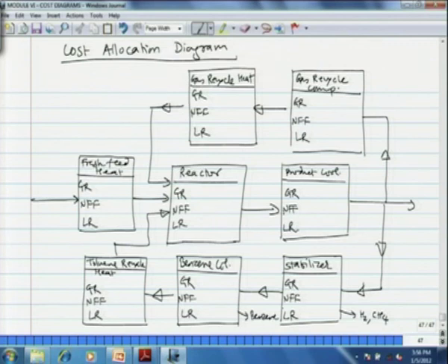I am showing now the products that come out of the stabilizer, H2 and CH4, and the product of the benzene column, benzene, and now we pick up all the numbers that are given in previous pages. Well, for reactor 153, 38, 9, for product cooling 74, 40, 18. These are adjusted to the nearest integer in some cases. Gas recycle compression 110, 0, 0. Gas recycle heating 161.300, or you can take just 161.